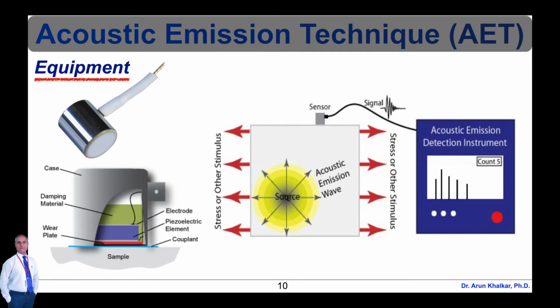Transducers are selected based on operating frequency, sensitivity, and environmental characteristics and are grouped into two classes, resonant and broadband. The majority of AE equipment is responsive to movement in its typical operation frequency range of 30 kHz to 1 MHz. For materials with high attenuation, that is plastic composites, lower frequencies may be used to better distinguish AE signals.